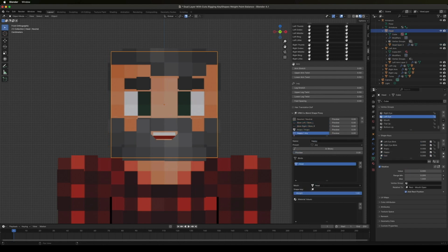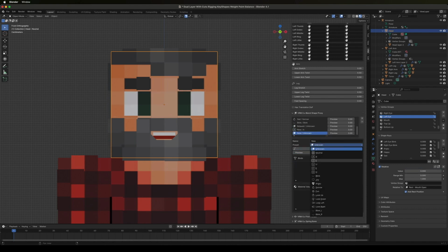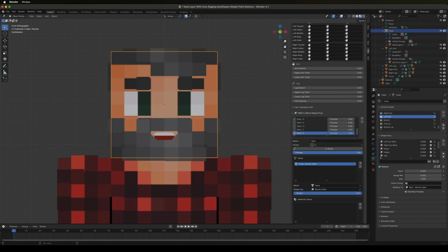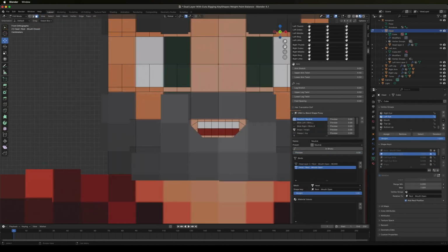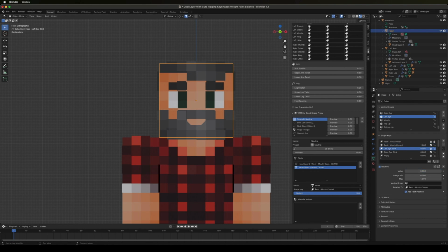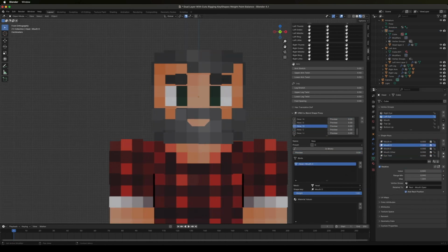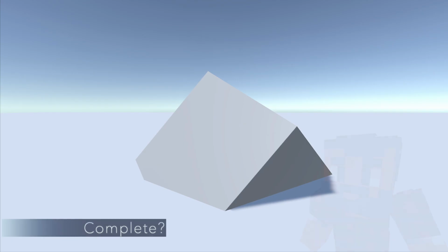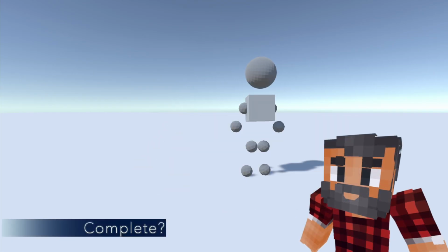Because we can combine multiple shape keys at once, in order for our character to blink with both eyes, we just need to make shape keys for winking with each eye and then combine them in the blink option. We can then use the preview button to see what sort of effect our blend shapes are going to have on our character. With all our shape keys assigned and checked out, we can save and export the VRM character. And the development of our vTube character is complete.